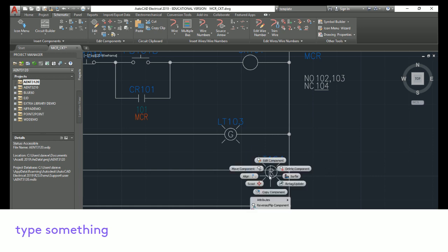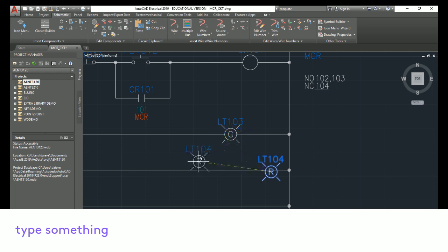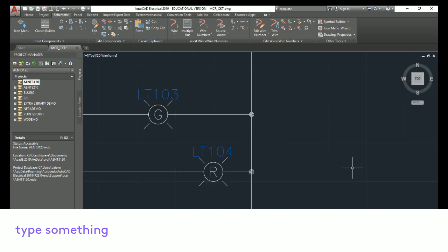You could go ahead and click on it and go to move, and I could click on F9, which is my snap mode, which will help guarantee that I get on that line because it's going to snap to that line. It's only going to give me 3 positions close, there, there, and there. So I'm not going to be able to get off by just a tiny little bit. So I'll snap it to the line there.